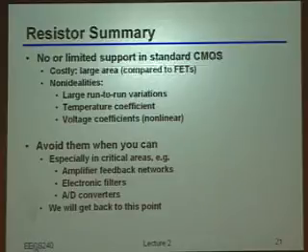So oftentimes, if you really want to get in the analog domain a large and precise resistor, it's going to take you quite a bit of area, at least compared to what the MOSFETs would have been. And even then, there's still going to be a lot of non-idealities. So run-to-run variations, they're going to have temperature coefficients, voltage coefficients, and so on and so forth. So the take-home message is that in many cases, you're going to try and avoid those resistors whenever you can. Okay?